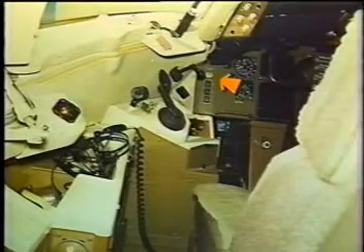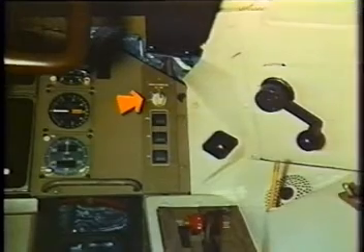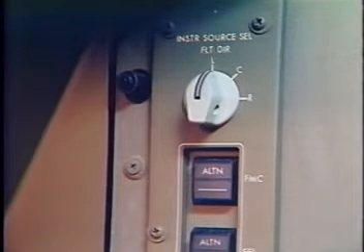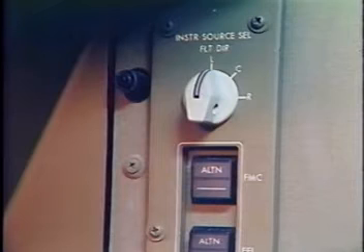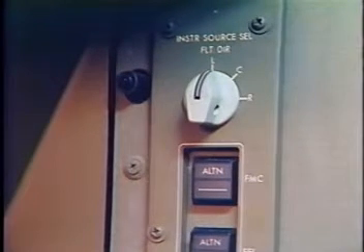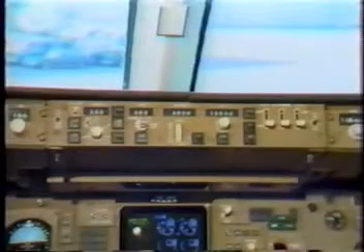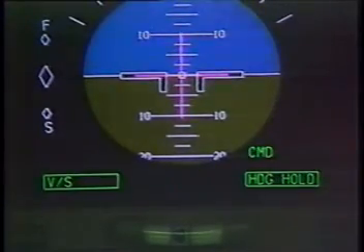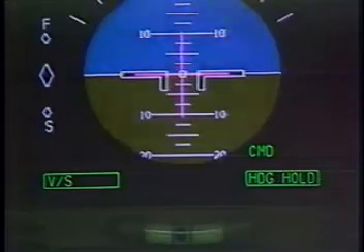Switches allow the captain and first officer to select either the left, center, or right flight control computer as the source for flight director commands and displays on the associated EADI. Engaging the left FCC to command causes the status display to change from flight director to Command.